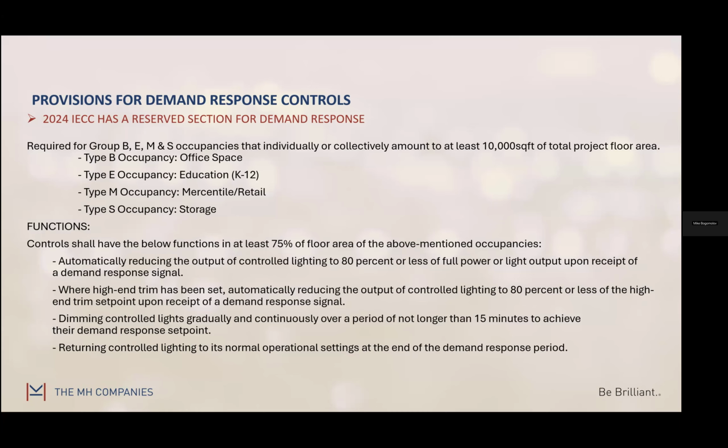So what does that mean for the control system? Is it saying that whenever I get this signal, now I have to get my lights up to 80%, even though I had them at 50? Or does it somehow need to recognize that it's sitting below 80 and then do nothing? There's a lot of if-then logic, basically, that would have to be built into your lighting control systems.